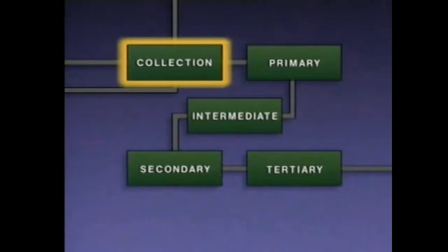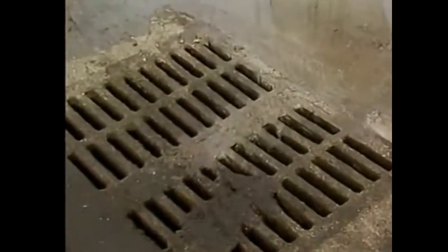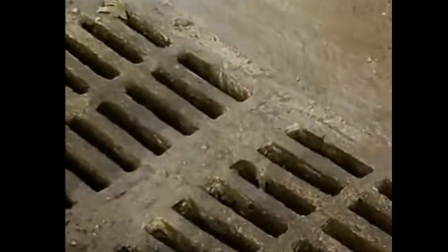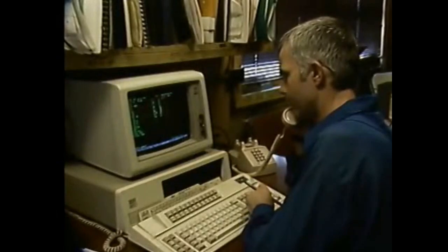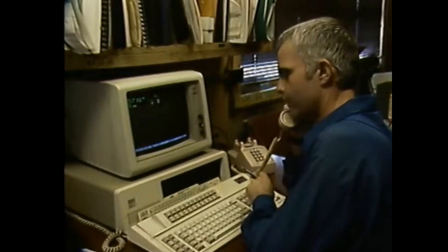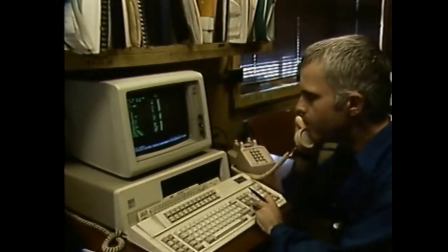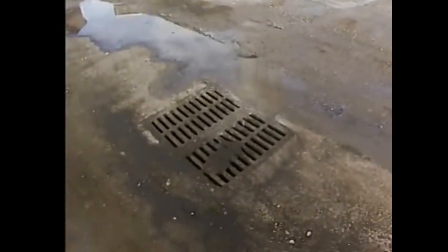He knows that the high sludge blanket level in the secondary stage could be caused by the entrance of wastewater with a high solids content. If water with a high solids content drains into the collection section, the solids could get carried all the way through the treatment system. Along the way, they would build up in the clarifiers and increase the sludge blanket levels. When he discusses the situation with other operators, the operator learns that there has been no significant change in the water entering the treatment system. So the collection section of the treatment system is probably not the source of the problem.